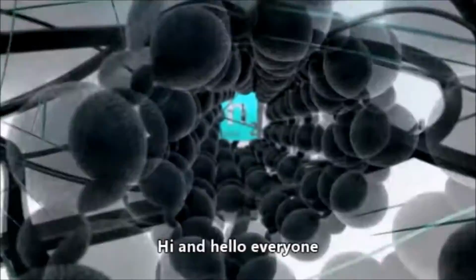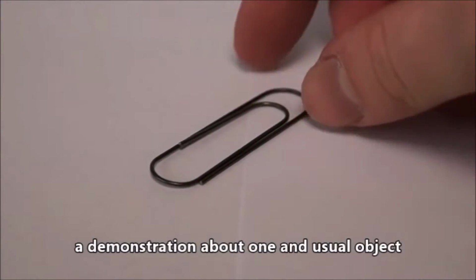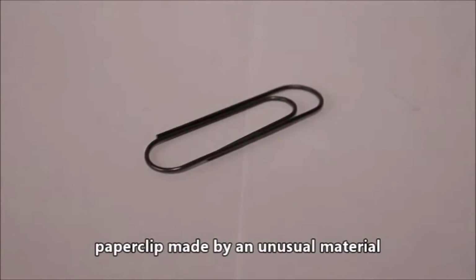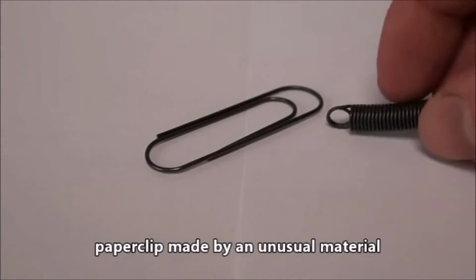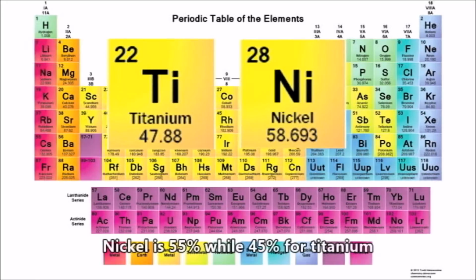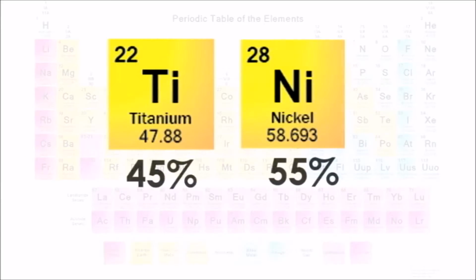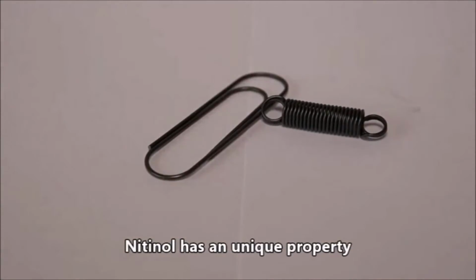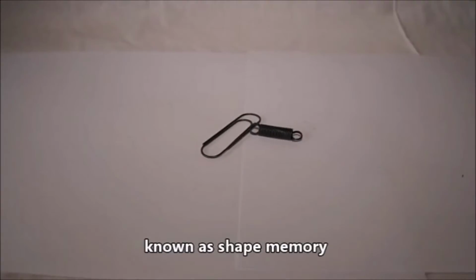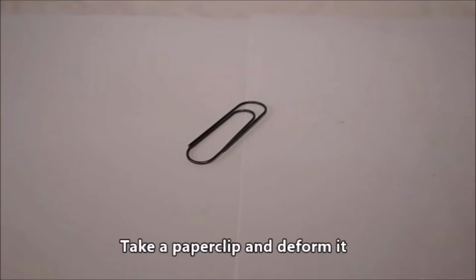Hi, hello everyone. Today I would like to show all of you a demonstration about one unusual object, which is a paperclip. The paperclip is made of an unusual material, which is nitinol. Nitinol is an alloy of nickel and titanium, where the proportion of nickel is 55%, while 45% is titanium. Nitinol has a unique property, also known as shape memory. So let's conduct a demonstration of this nitinol.